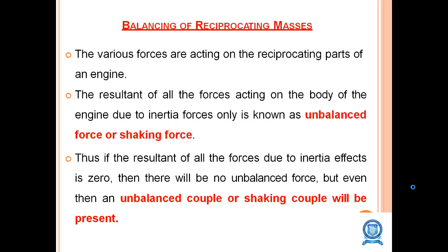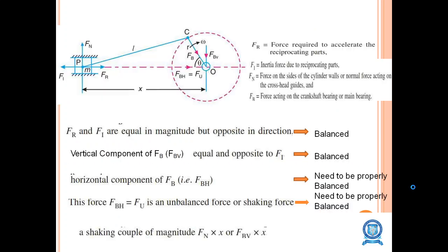So balancing is nothing but the various forces which act on reciprocating parts of the engine. The resultant of all the forces acting on the body of the engine due to inertia forces is known as unbalanced or shaking force. Thus, if the resultant force of all the forces due to inertia force is zero, then there will be no unbalanced force. But even then, an unbalanced couple or shaking couple will be present.